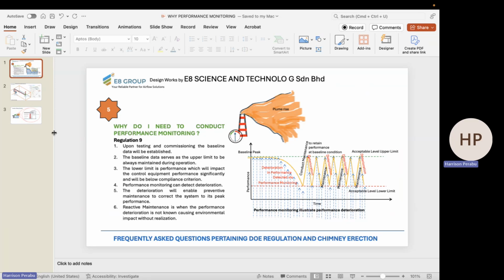Why are we removing at the point of generation? We're removing at the point of generation so that these airborne pollutants do not get introduced to the breathing zone of a worker. So that's why we design LEV. But what we derived at the hood is going to serve as a basis for everything else.